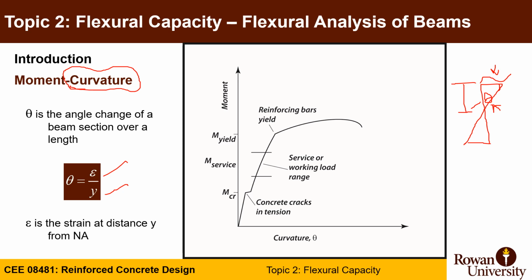And here again, we are showing the moment curvature diagram. You have the cracking moment, which separates a state where concrete is not cracked and a state where concrete starts to initiate cracks. You have service moment, which is part of the curve between cracking and yielding. Here is a point where the first onset of reinforcing bar yielding, and here is the maximum moment, which we often correspond to nominal moment or even ultimate moment if we apply the resistance factor reduction.